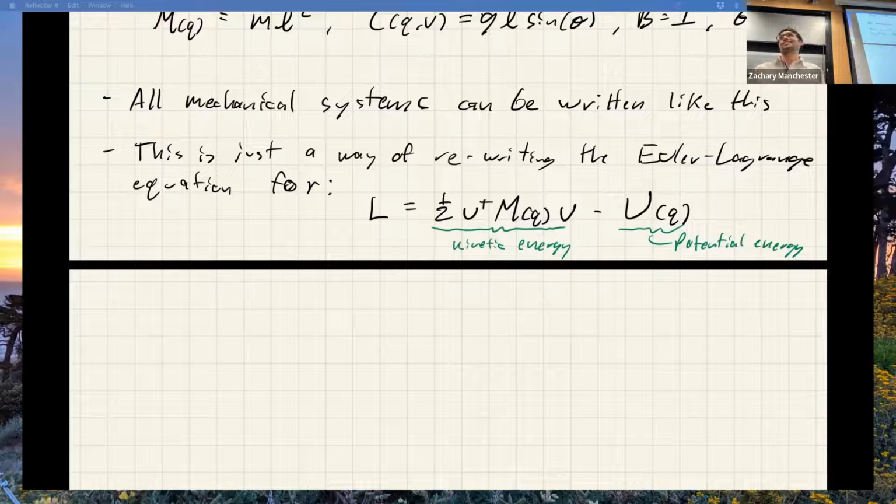They're not actually the same thing. They're only the same in a Euclidean reference frame, only if you use Cartesian coordinates. If you choose generalized coordinates that are not nice Cartesian coordinates for a point particle, for example a robot where you use a quaternion for the orientation and joint angles for the limbs, then this isn't quite F equals MA.